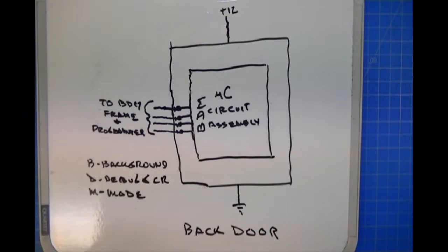So they came up with a technique which is really slick. It's also really complex and very sophisticated, called the background debugger. The background debugger mode in most cases will only use a single pin on the processor in order to get data to go in and come out.